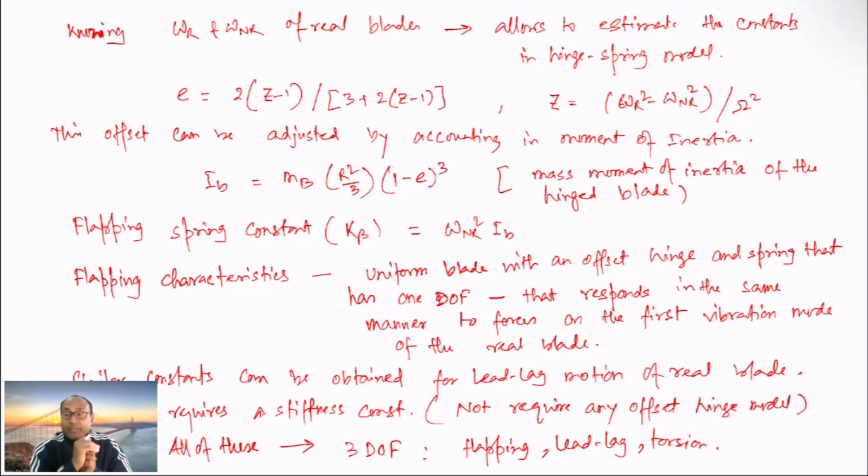That would have 1 degree of freedom, and it responds in the same fashion to forces as the first vibration mode of the real blade. That means this would behave in the same fashion as the real blade responding to the vibrational mode, so that you obtain similar characteristics.